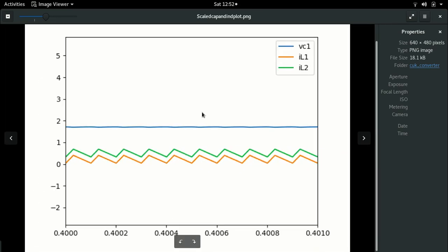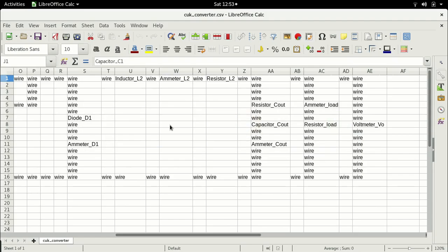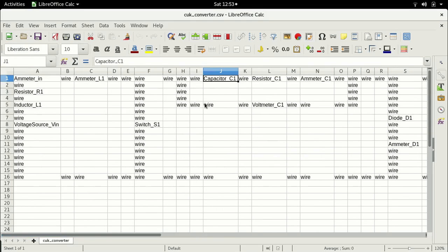We have decoupled the input from the output, and we have placed this energy decoupling capacitor, which now takes energy from the input and transfers it to the output. So this is how the capacitor plays a role in this filter. Now, of course, I would encourage you at this point of time to try to play around with the value of the capacitor. Try to reduce this capacitor and increase the ripple and see how this operation changes, right?